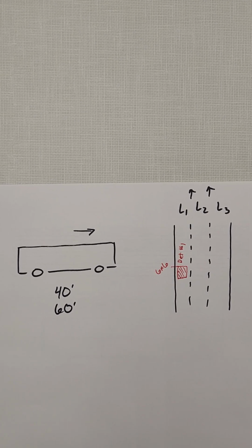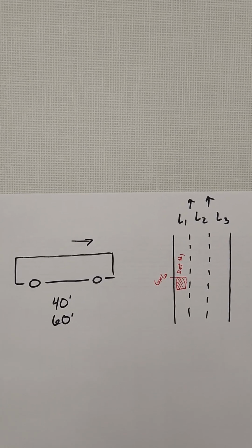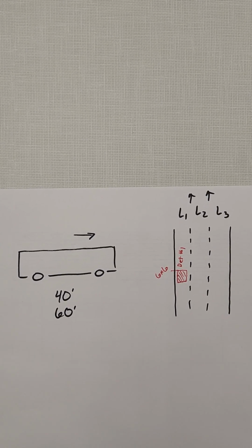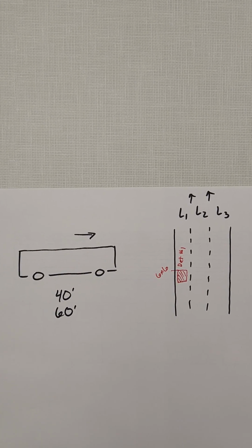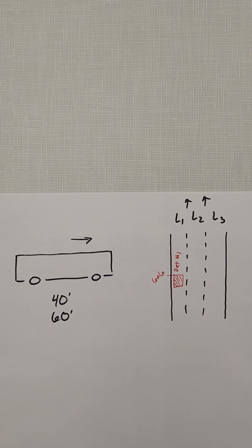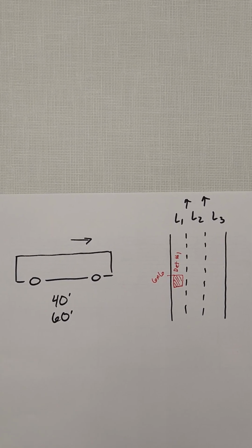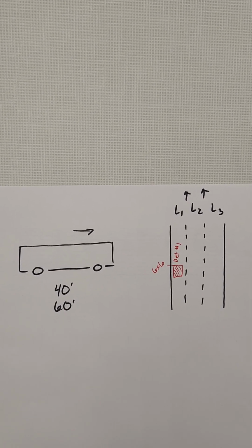I wanted to share an operation that we've found success with that uses just basic detection zones. It could be a loop detector, it could be video detection, and a couple logic steps to get transit signal priority or signal control priority (SCP) detectors up and running. A very low-tech solution, but it can provide pretty good operations.